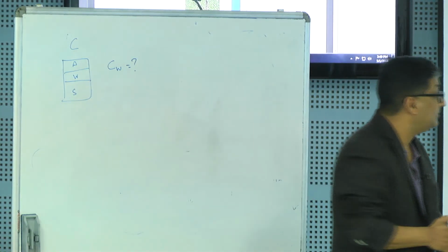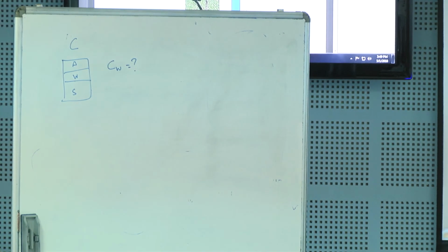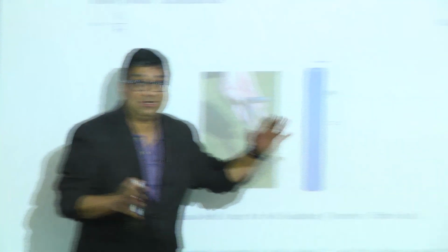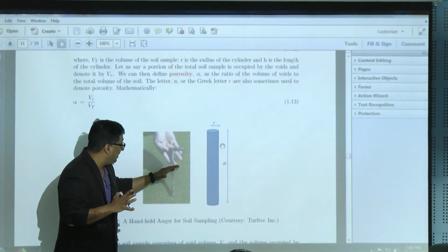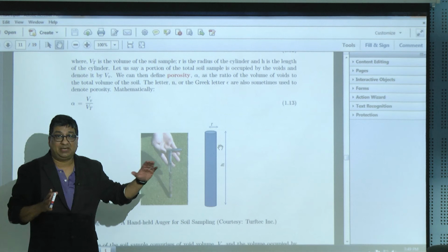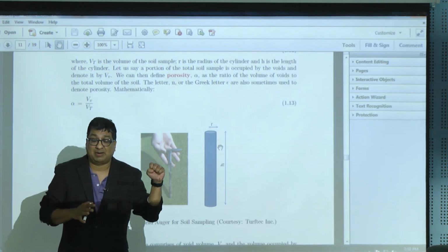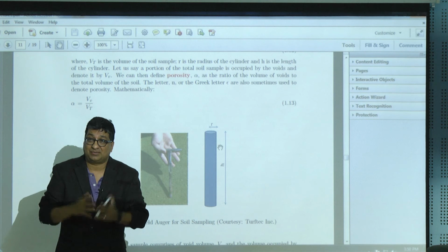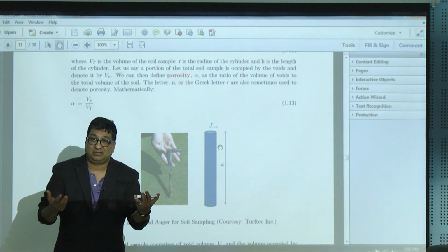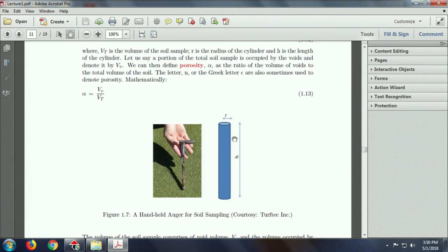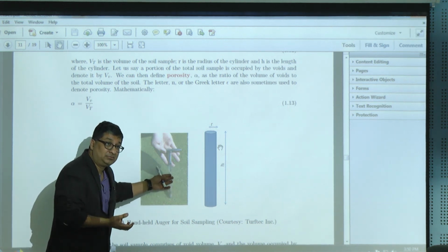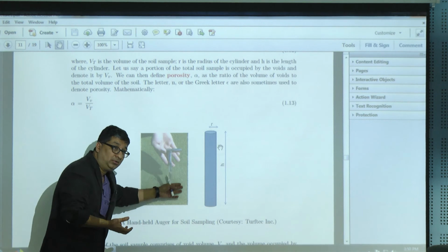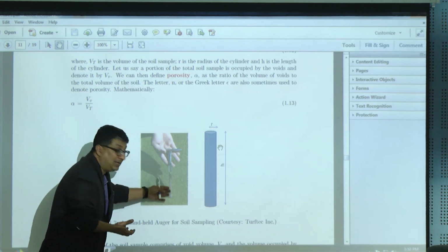Okay. So when I take the sample, I can only take the sample of the entire soil. Okay. Because in the vadose zone, it's very hard for me to get the water sample by itself. It's possible, but it's very difficult because there's not much water. Okay? So I have very little water. So because of that, chances are I don't usually measure what's the concentration. I can't separate out that water. Okay? What I get is the total concentration.